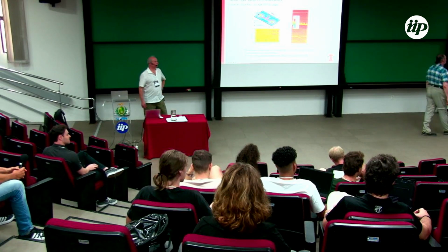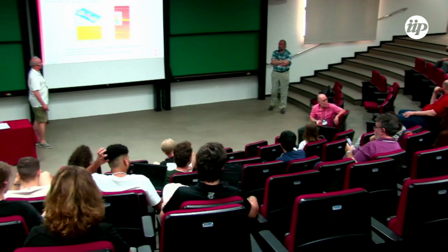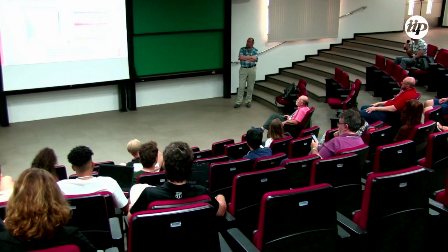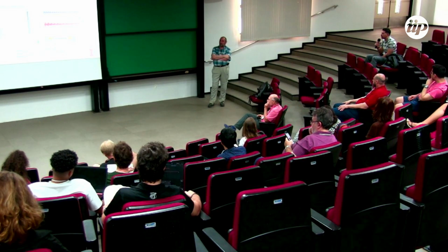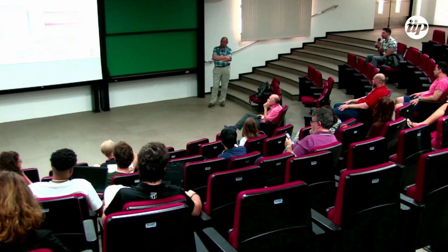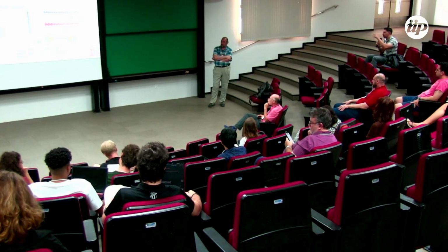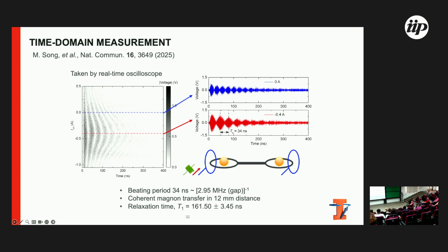Thank you very much for the talk. I have a question on this experiment, where you put the two loops on the side there. You mentioned that they're placed in a way that you don't get any interference from the loops that you were measuring. How do you not get crosstalk from the superconductor? That's relatively easy. That's just by having the antenna perpendicular to the resonator, right? So the magnetic fields of the resonator are in this direction, and the antenna is only dependent on the perpendicular direction. But they don't contribute to any simultaneous drive from one to the other on the magnon. Because I think what we found is even if you have fields that are meant to be perpendicular, once you place the magnon in, then you do get some mediated crosstalk between two things like that.